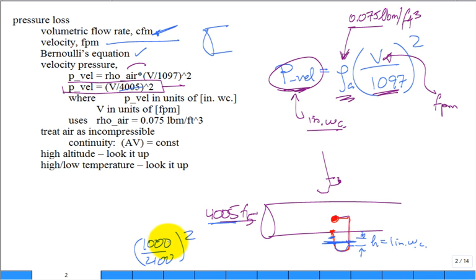All right. Anyway, what I just said about inches of water column is in feet per minute, and the density of air is this much. Well, why in air conditioning systems, if you haven't been emphasized before, do they always treat air as incompressible? I learned air is compressible, especially in thermodynamics, right? We beat the students up, said liquids are incompressible, but it's a bad approximation for air, ideal gases. But the air in these systems undergoes such a small pressure variation that it's treated as incompressible.